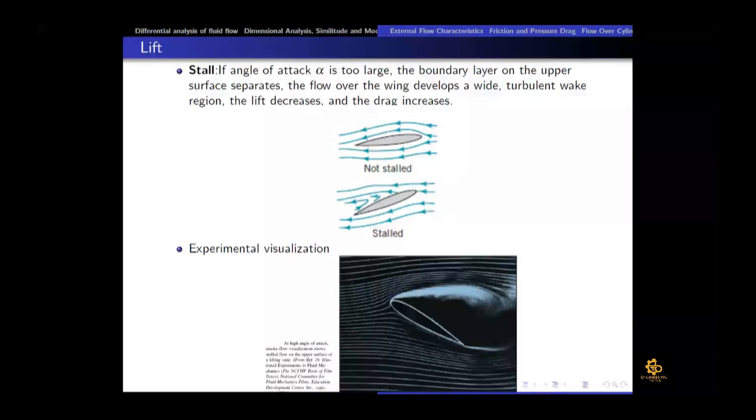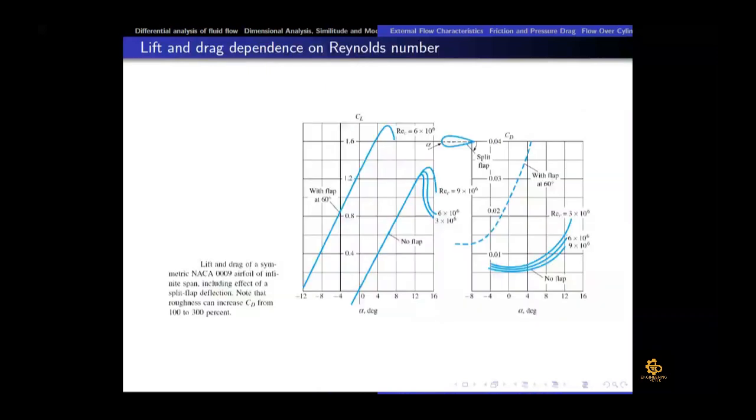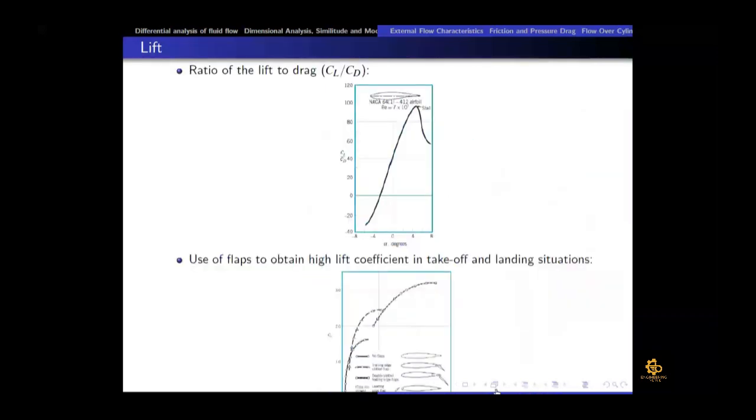There are some kind of flaps on the trailing edge. Those flaps are used to create additional lift, right? If I show you the figure for that, you can see some movable flaps on the trailing edge. If we make it more downwards, there would be more pressure on the lower side. It means that the lift force would be more.